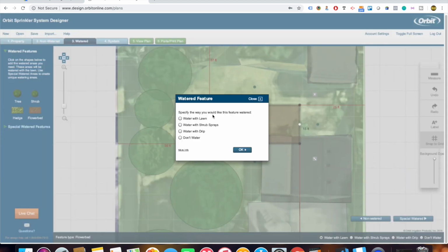As I select a flower bed, you'll see that it gives me the options for how you want to water those. These I'm actually going to use a specific drip line, and I can tell it what type of watering I want. Emitter tubing, there's PC drippers. I'm just going to go with drip zone. That's going to bring its own zone up there to that section, and then I can use an actual drip manifold to determine what type of watering I want.